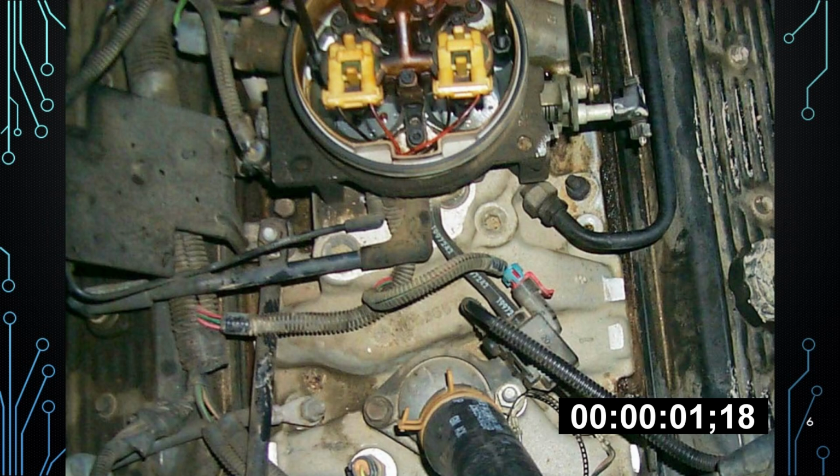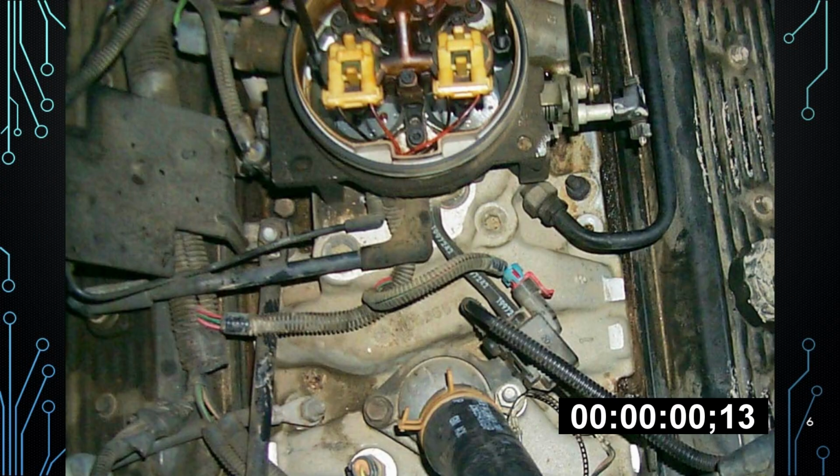Do you recall what pressure most of these worked at? This was a General Motors, so what was the fuel pressure that was normally seen there? General Motors throttle body injection systems typically operate at around 9 to 13 psi. It's a low pressure system compared to modern multi-port or direct injection, which are much higher. What was the history of these as far as serviceability and reliability?